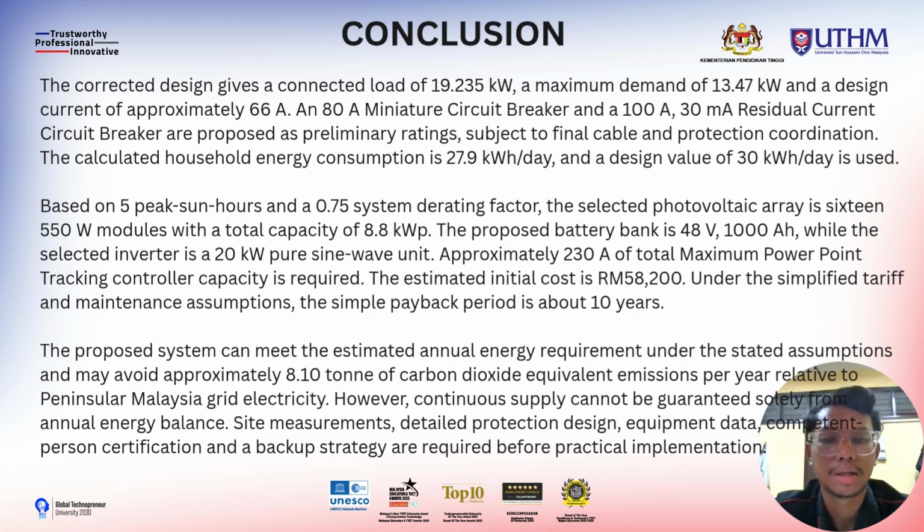The proposed solar system consists of 16 550 watt modules generating 8.8 kilowatt, paired with a 20 kilowatt pure sine wave inverter, a 48 volt 1000 Ah battery bank, and a 230 amp MPPT controller capacity at an estimated initial cost of RM 58,200.